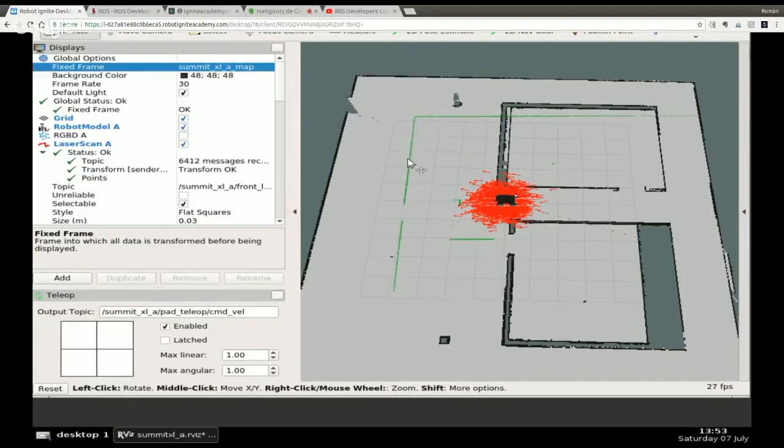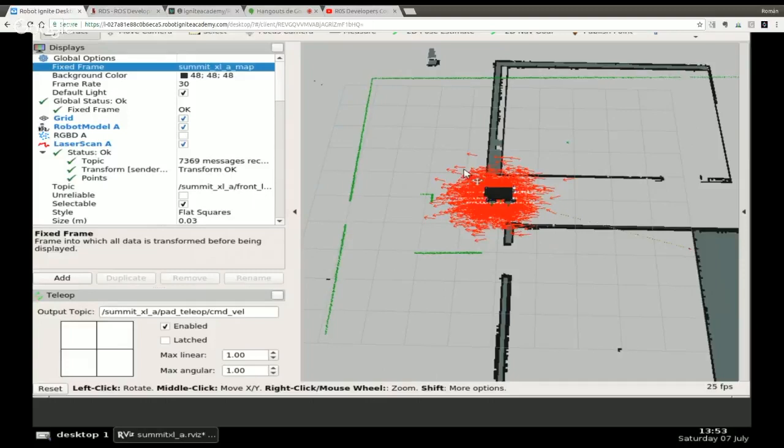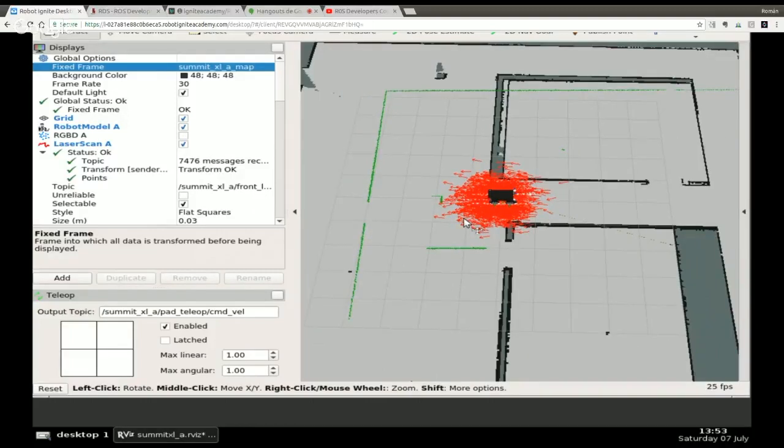As we can see here, the localization is not the correct one because we don't have a match between what the robot is reading from the laser scan and the real map. You can also see that the dispersion of the particles is too big, so we need to reduce this dispersion to have a good estimation.